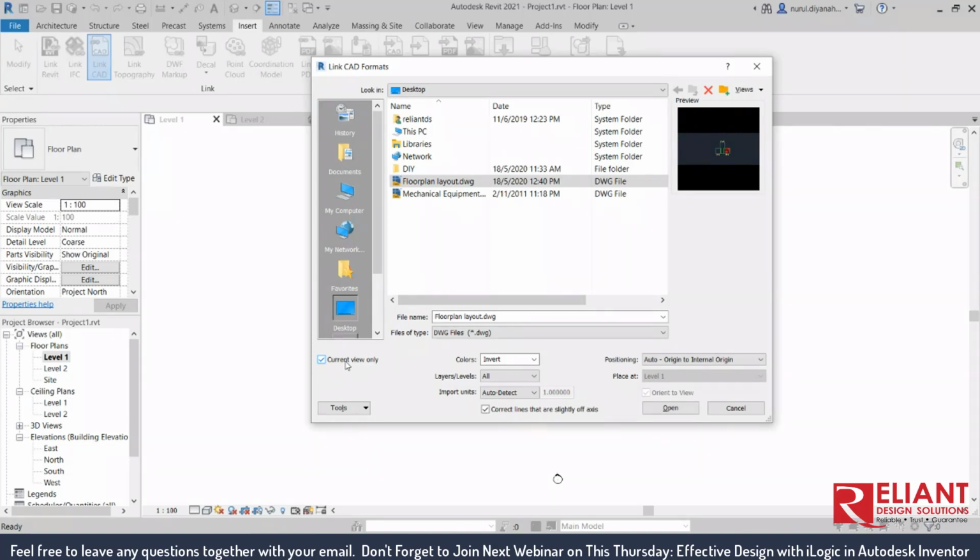But if let's say the drawing that you want to bring in, either link CAD or import CAD, contains things like doors, HVAC, or electrical switch box, then it's better for you to leave the checkbox empty. So I will not check it, for me to show you guys how it will be displayed inside the view. Click open.